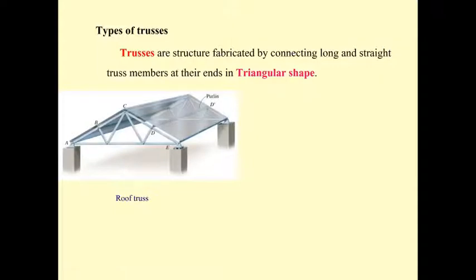Okay, by that way, when we use this building, the building may be subjected to wind load. When it's subjected to the wind load and the rain, that load is going to hit the metal sheet first, and then it transfers the loading along the length of the purlin. So the purlin is going to be subjected to a uniformly distributed load along its length.